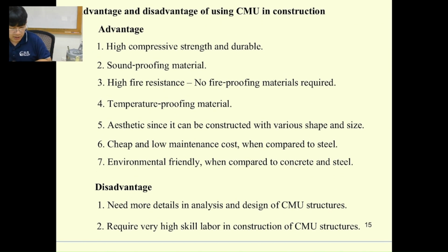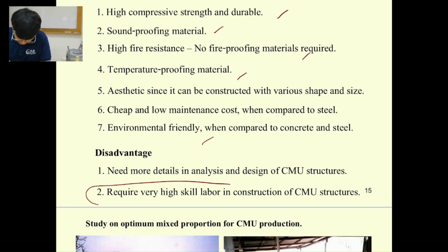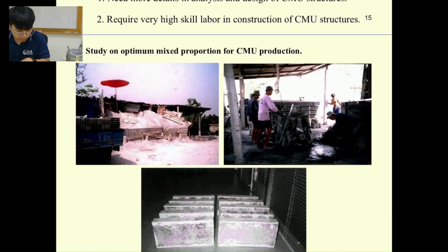And these are the advantages. It's similar to the clay brick, the one that we just passed previously. So it's going to have really high compressive strength, and it is soundproof, fire resistant, and temperature proofing material, and cheap with low maintenance and environmentally friendly. But it also requires, I think this one may not require really highly skilled labor as the clay brick, but it also needs somebody who understands the clay work in order to construct it. Okay,